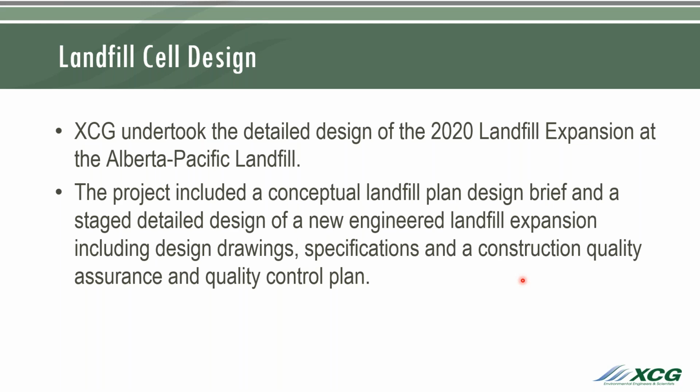So the project included a conceptual landfill design brief and then staged detailed design of a new engineered landfill expansion. The staged detailed design included drawings, specifications, and a quality control and assurance plan for the construction of the landfill.